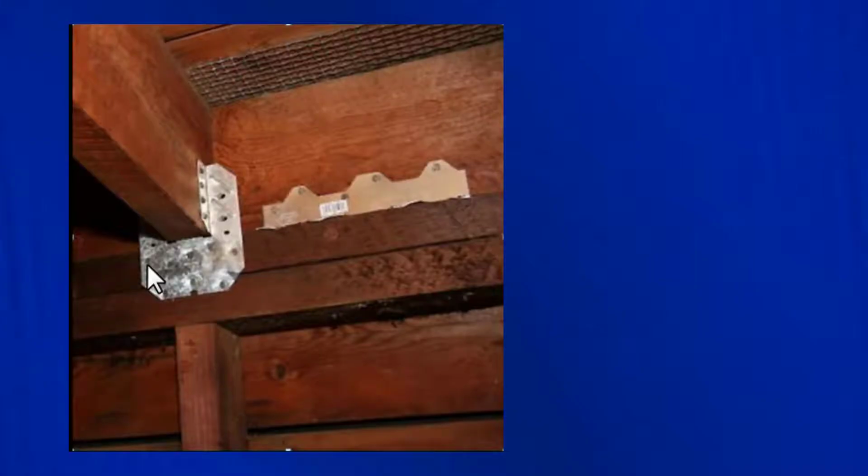Here you see 2 floor connectors. This right here is the top of the cripple wall. Now this floor connector here is called a type E connector in the FEMA P1100. And the way this works is this nail and then this nail and then this nail, they nail into this board right here. And there are some other nails that come down this way, and they attach to the top of the cripple wall. And that way, when the floor tries to move, it goes into this type E connector, and then that goes into the top of the cripple wall, which is what we want to have happen.